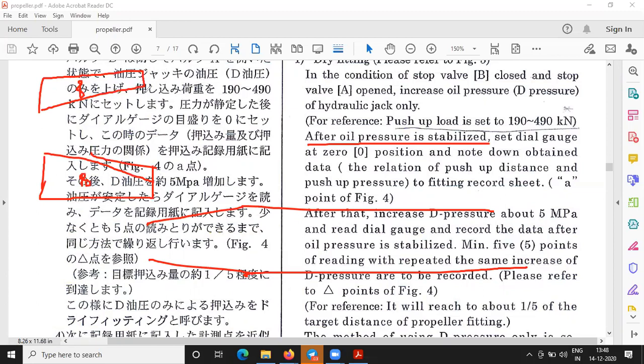When this part touches this part and starts moving up, suppose when it is touching at this point, there is sufficient gap created here. It will be something like that: whereas the top portion is touching, the bottom portion has got some gap. Again, you start pushing it up, and at one point, what happens? The proper alignment of this boss and this shaft takes place.